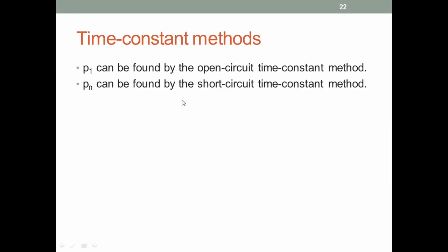And then we say that the time constant method allows us or defines p1 to be found by the open circuit time constant method, and pn by the short circuit time constant method.